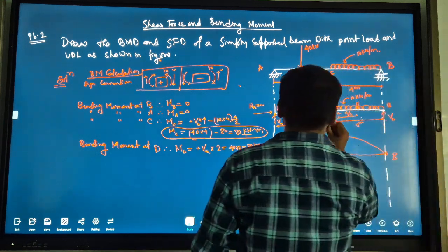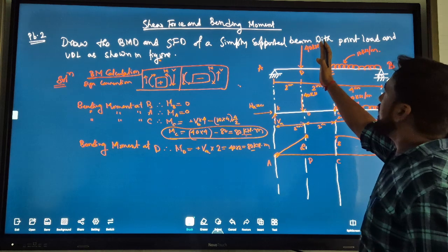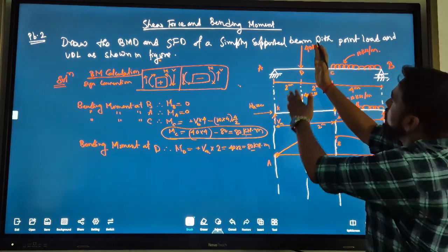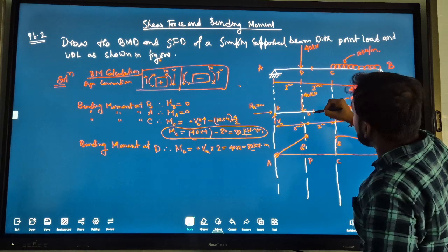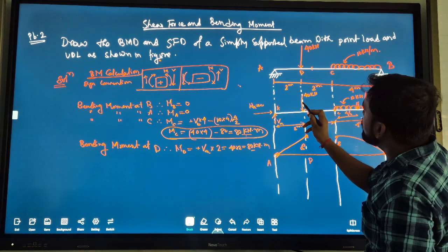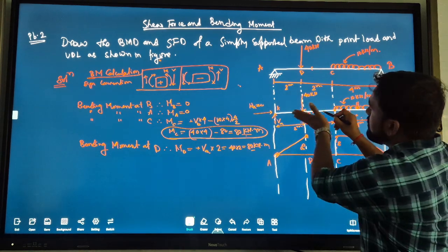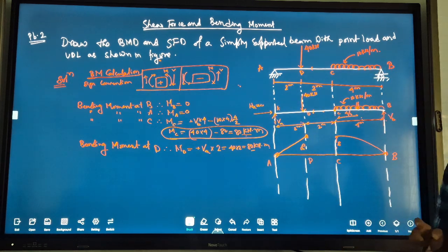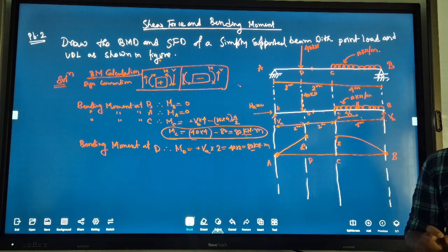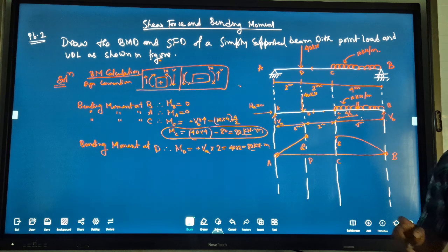It's a straight line because, if you stand here, there are two vertical forces, VA and 40. If you stand on this side, again VB 40 and point loads only. Always point loads, so join by straight line, not by curved line.